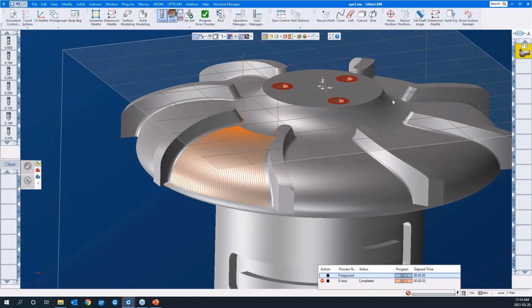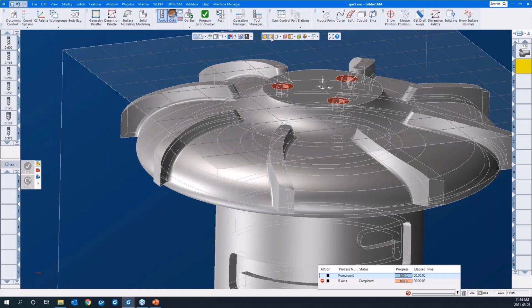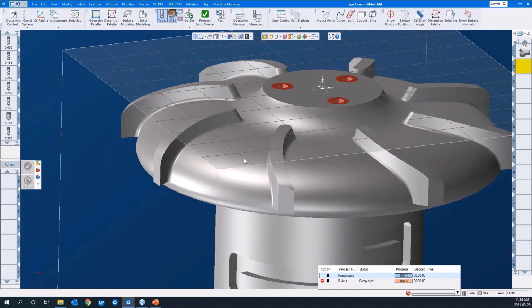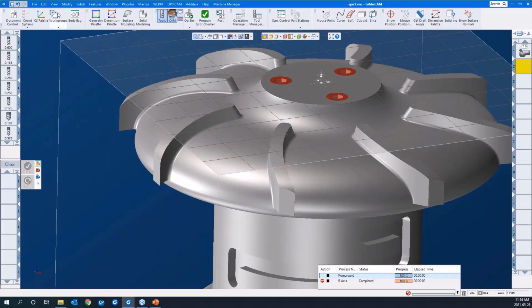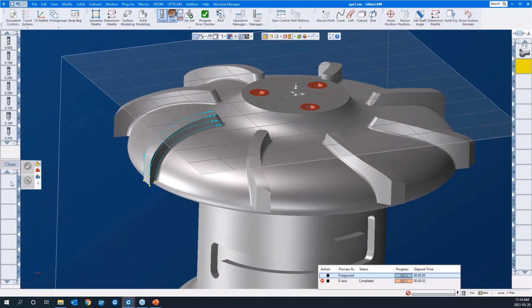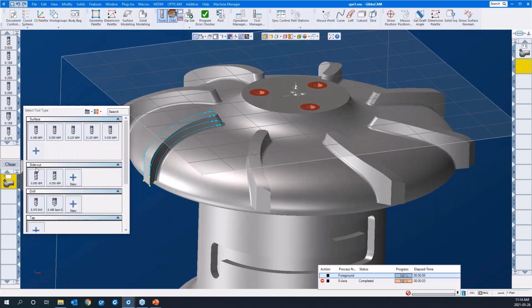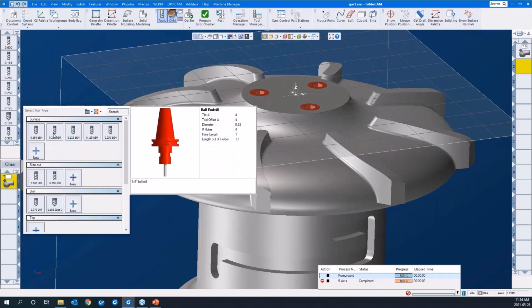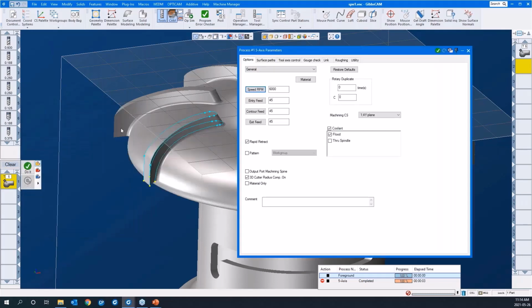Okay, in this last example, this last toolpath, I used the edges of the solid to select. Well, you certainly can do that, but you can also use geometry that you have extracted from the solid. And I can do that in this case here. I'll create another 5-axis strategy. I'll use the same tool. Cutter comp is on by default. I'll turn it off until required.